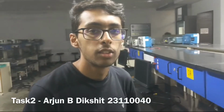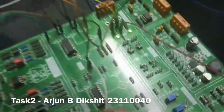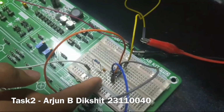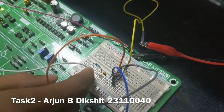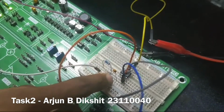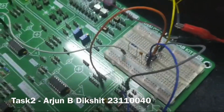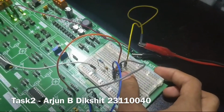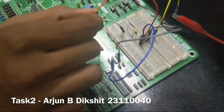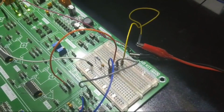So for the second task, we've implemented a differentiator based high pass circuit. The output of the analog multiplier is fed in as an input to the op-amp in terminal 2, inverting terminal, through a series of 1.5 kilo ohm gain flattening resistor and a 10 nanofarad capacitor. The feedback resistor is also 1.5 kilo ohm and is connected to the output. The non-inverting terminal is connected to the ground, and the op-amp power supply is connected directly to it.